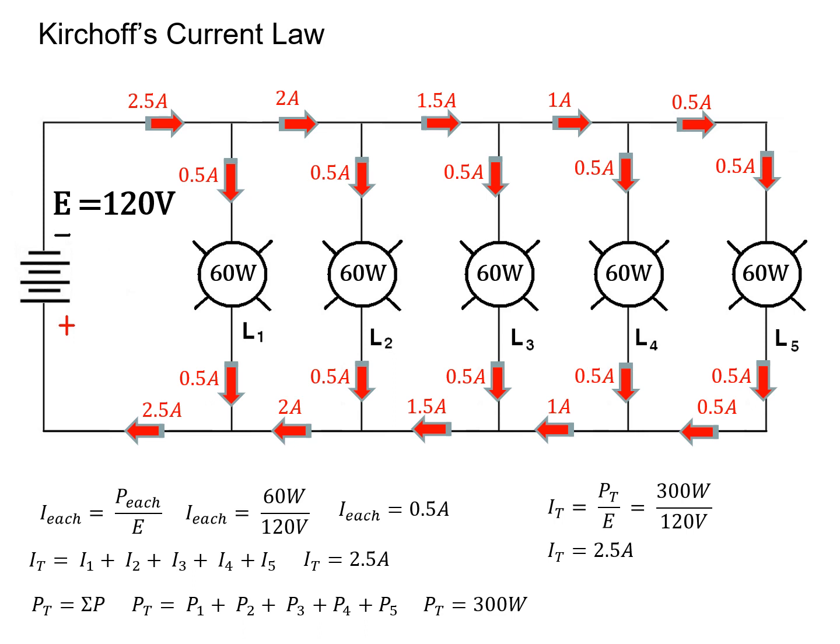We have to understand this concept of how the current breaks up between the branches, or adds, depending on which way you're looking, and the distribution of the currents. We also have to take with us, to help us solve these problems, that powers add, or the load powers add, and that all the powers together have to add up to the source power.